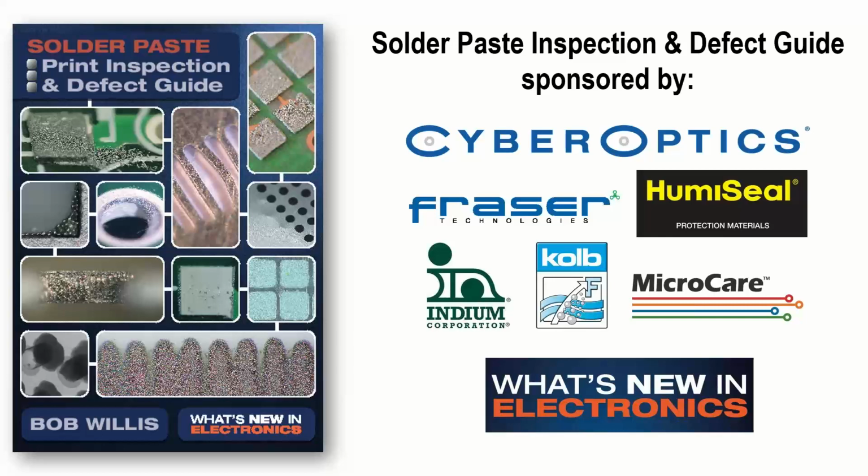So you'd start off with a number, and then what you'd want to try and do is reduce that number. So let's say you do a clean wipe or a wet wipe or dry wipe every some number of cycles, and then slowly decrease that, but compare the information with your SPI data or your other defect data. That's really the only way. And I'm not trying to avoid the question. It's just a fact that your process will be different from every other process. So really, you've got to start off with a number, and it's going to be more frequent, and then slowly decrease the frequency and find that crossover position.